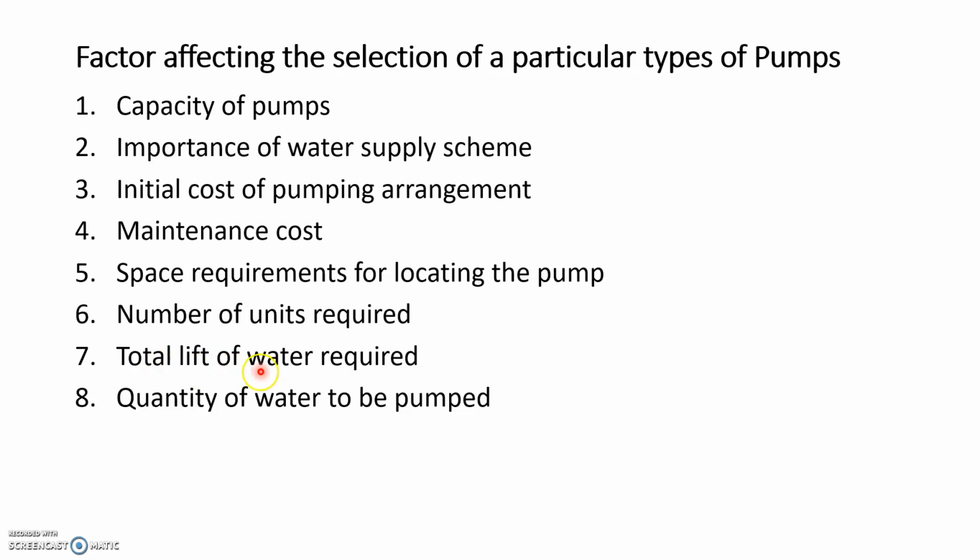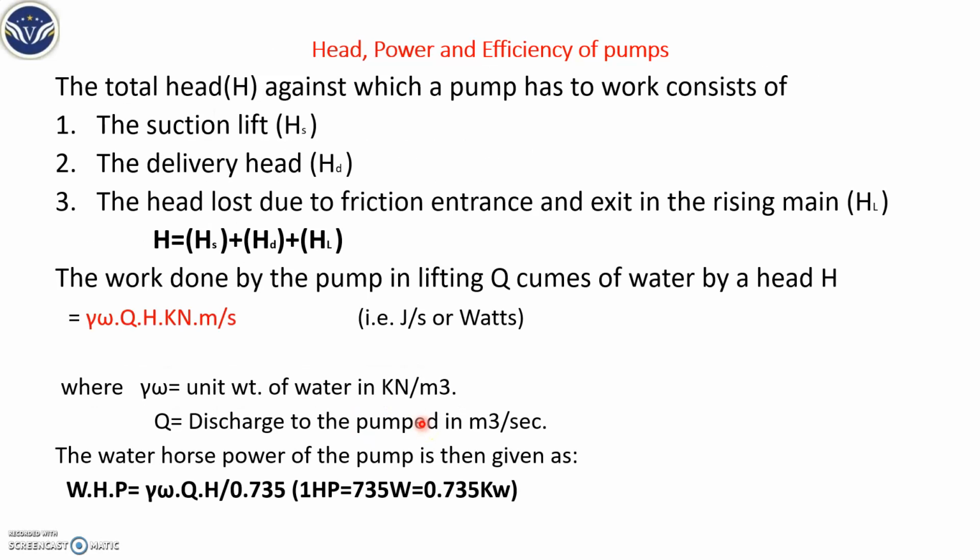So what will be the quantity, how much head you are lifting up, and the total quantity of water that needs to be pumped. Next, there are certain formulas based on which we calculate the horsepower and so on. The first one is total head. Total head consists of suction lift, delivery head, and the losses.